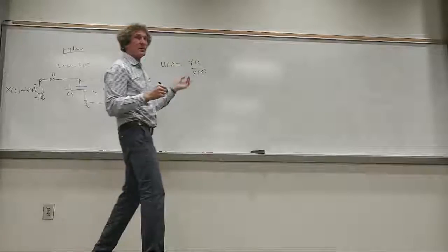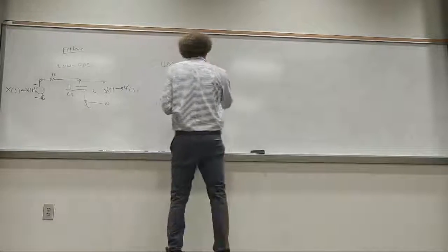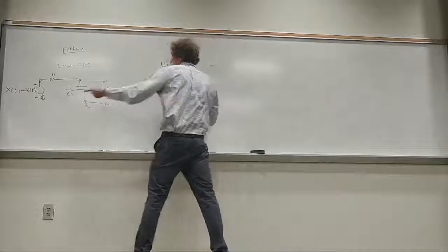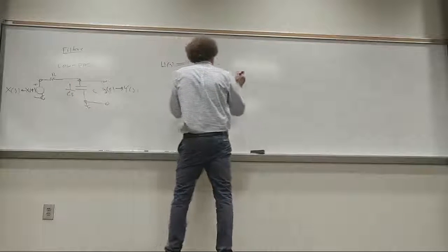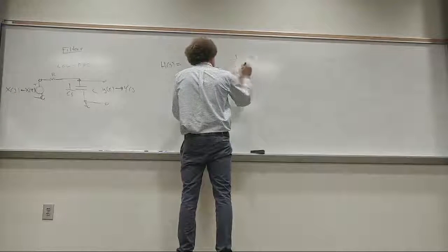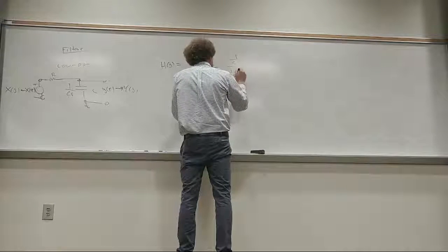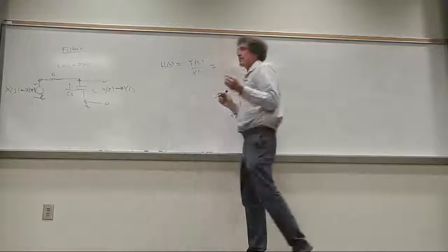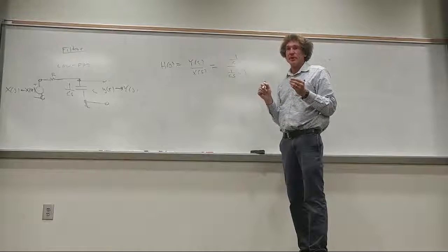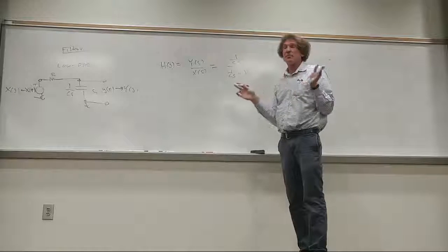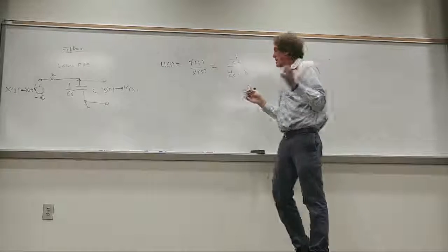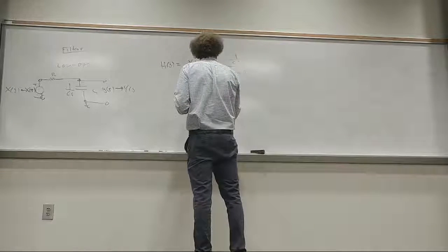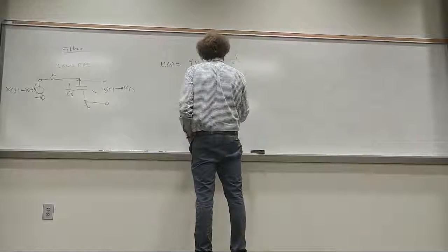So this is the output, this is the transfer function. Well, here, Y of S, this is simple voltage division, so it's that impedance. So it would be 1 over CS over 1 over CS plus R. Do you all agree with that, class? Simple low-pass filter, agree?